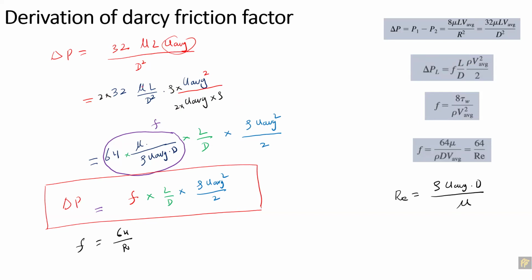And then I have written here the mu and L by D square. But actually we need the L by D here, so we have to take the 1D from here, and this will become the L by D. So I've taken the mu here and the 1D from here as a D here. I've taken the U average from here and put it over here. And similarly, I got the one density in the denominator, I put it over here. So this whole thing is the friction factor.